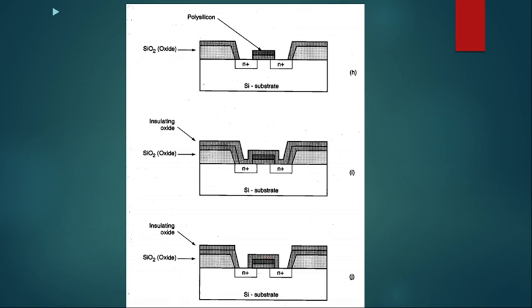Now, till now the MOSFET, metal oxide semiconductor, is defined, and source, gate and drain are defined, but now we have to make it Nmos. For making it Nmos, the channel should be of N type, so it will become N type when N plus impurities are doped into it. So what is N plus? N plus basically means highly doped.